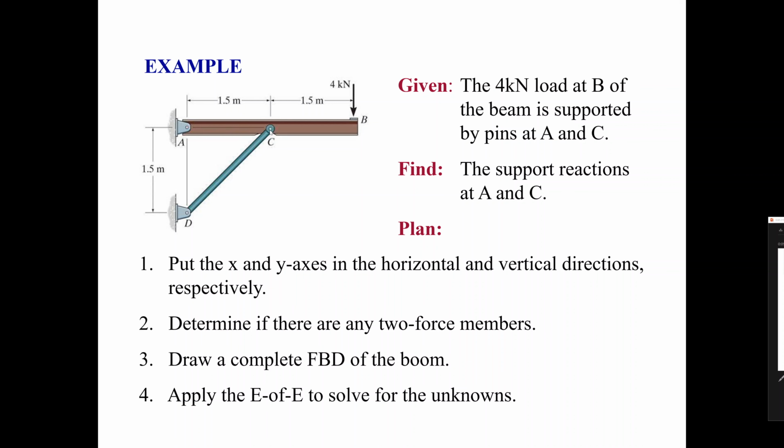You could probably tell that it's going to be a force that's equal and opposite, pushing back up at point C. But you might not know the direction. So what we'll do is draw a line of action, a force heading from D to C, off in this direction of the beam, the connecting rod.